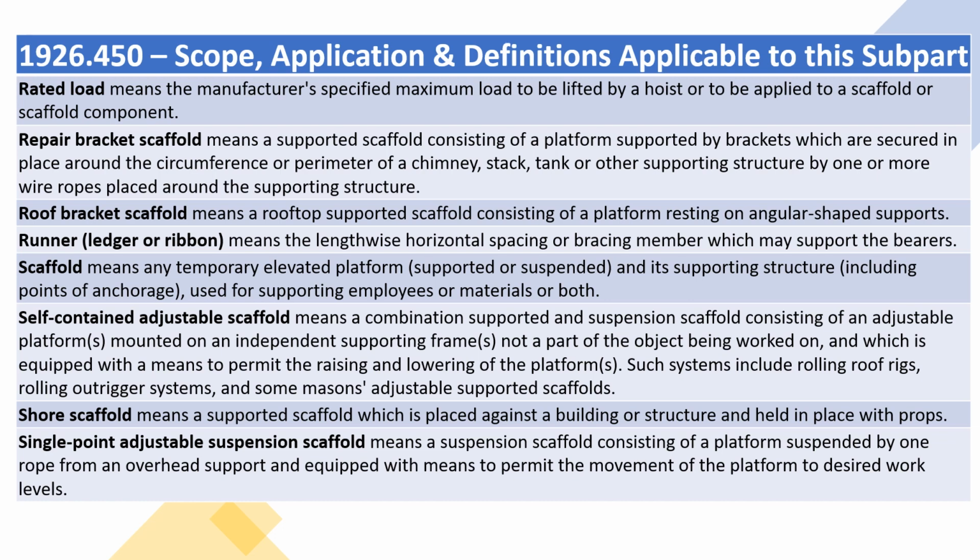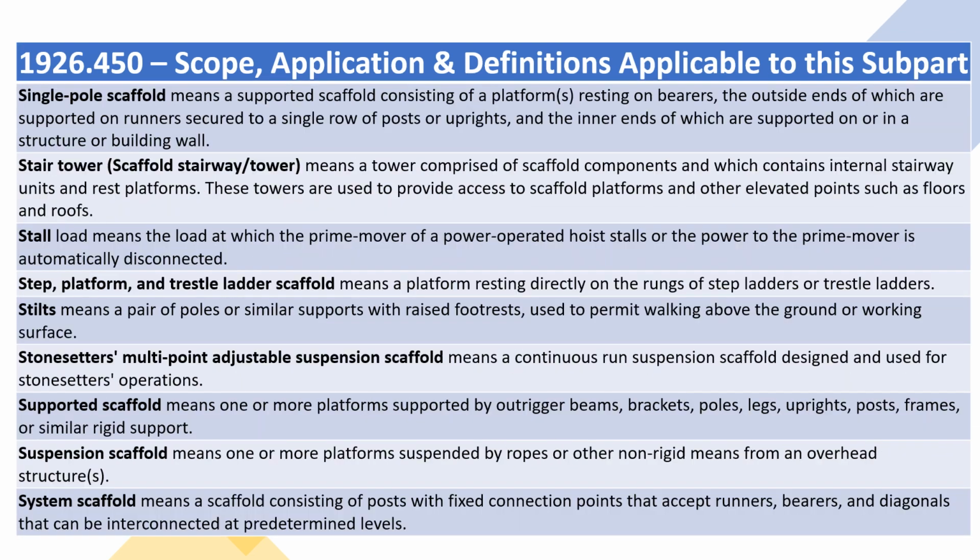Shore scaffold means a supported scaffold which is placed against a building or structure and held in place with props. Single-point adjustable suspension scaffold means a suspension scaffold consisting of a platform suspended by one rope from an overhead support and equipped with means to permit the movement of the platform to desired work levels. Single-pole scaffold means a supported scaffold consisting of a platform resting on bearers, the outside ends of which are supported on runners secured to a single row of posts or uprights, and the inner ends of which are supported on or in a structure or building wall.